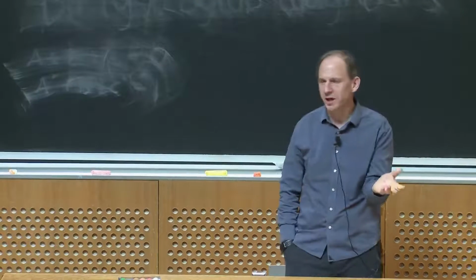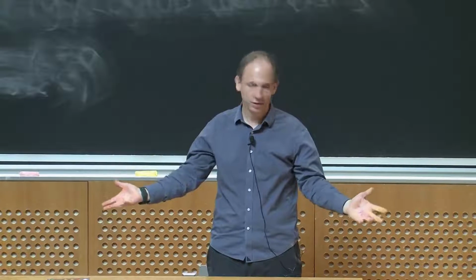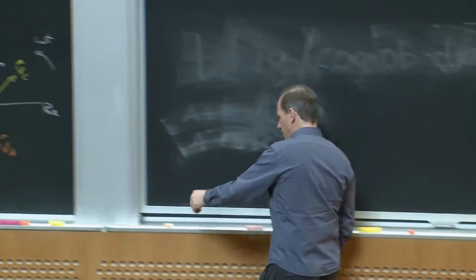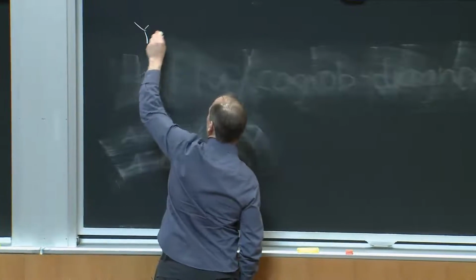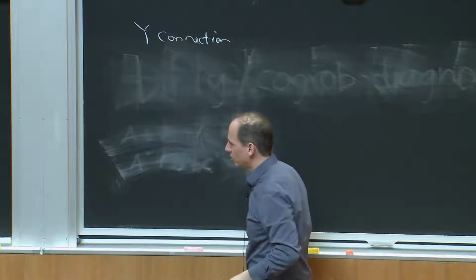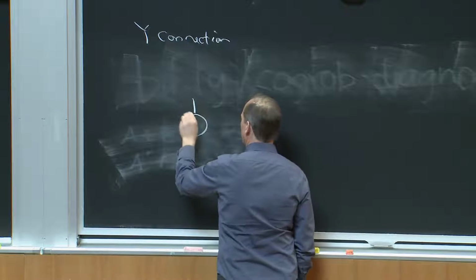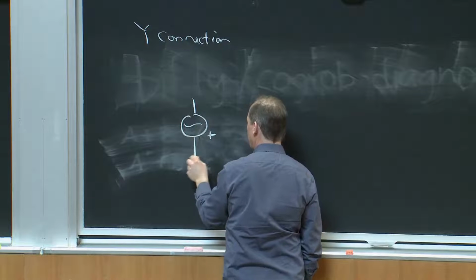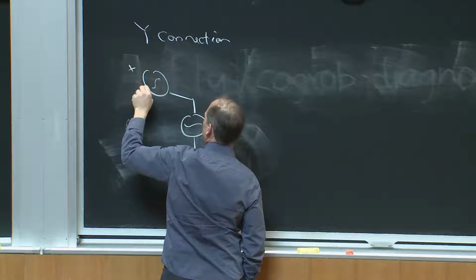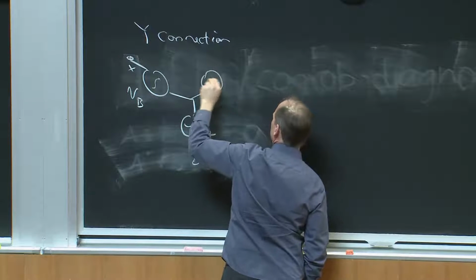There's different ways we might connect these 3 voltage sources. So suppose I create 3 voltage sources this way. The most typical way you see a source connected is in a so-called Y connection, also historically sometimes called a star connection, and one might do that this way. Maybe I would have VA, VB of t, and VC of t.